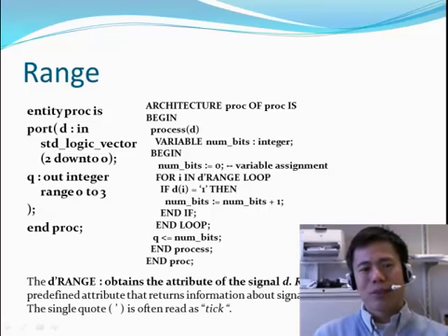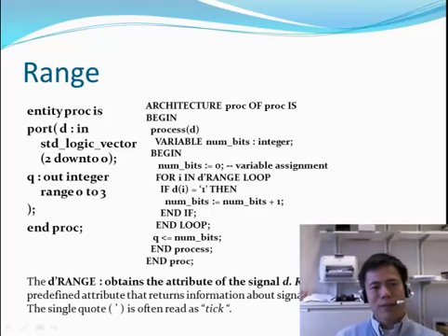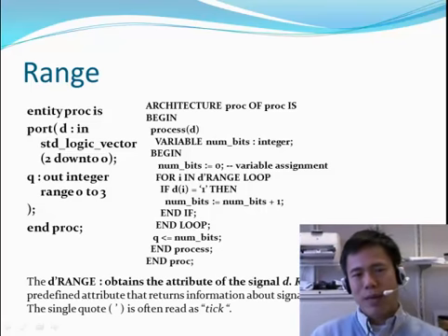So what you have to do is design something similar to this in VHDL that will implement the function of a decoder. With this range and this process, the process syntax will start from the reserved word process, followed by any signals in the sensitivity list, and followed by the variables you may need to use in the process. You can define them here, followed by the begin keyword, and the end process keyword.